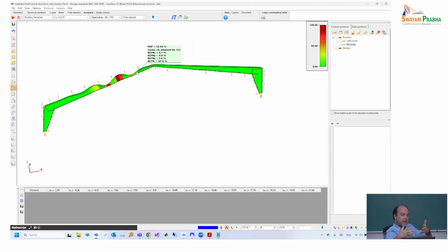All these eigenvalues are not millimeters, they are just numbers. You can convert them into imperfection by multiplying with a scaling factor to change them into millimeters, but they are just numbers. It doesn't matter. You can say let's multiply them with 1 millimeter, and now they are already deformations. They are continuous deformations around the structure. They fulfill all the compatibility requirements, as we saw on the first day when we talked about continuity of adjacent members. The rotation of the connected elements makes sense, so they rotate together based on the stiffness, based on the elastic stress level.